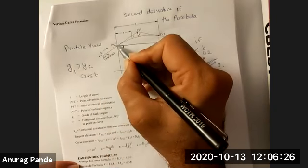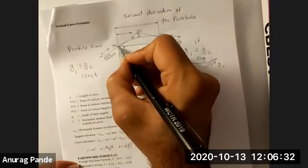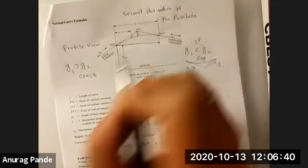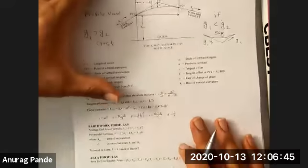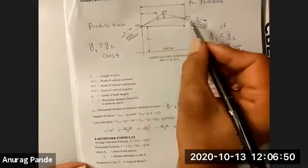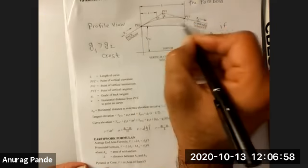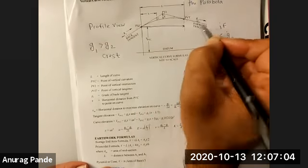It provides a smooth transition because the rate of change of grade is a constant, and you are able to go from grade G1 to a grade of G2 at a constant rate. The rate of change is constant, and that provides for a smooth transition. And that's just the answer to why we provide a parabola, because it provides a smooth transition between the first point grade and the last point grade. And basically what keeps happening is that you go from G1 at some point, and if you're transitioning between an upgrade and downgrade, at some point you hit the grade 0, and then you go to G2.